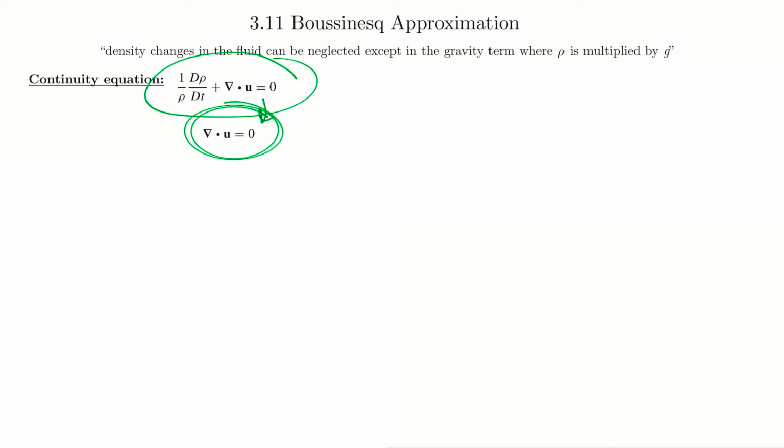So there are a number of different situations where you would have to consider the density variations, something to keep in mind. Now let's consider that the compressibility effects are small and say that the density changes are caused by temperature changes alone, like in a thermal convection problem. In this case, our Boussinesq approximation applies when the temperature variations in the flow are small. So we can assume that our density changes with temperature according to this expression here. Alpha is known as our thermal expansion coefficient, and it equals this.